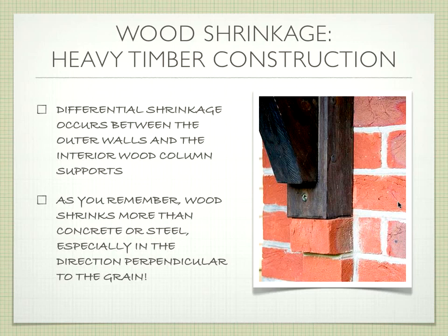If we go all the way back, I'm trying to review for you a little bit. The final's coming. If we go all the way back to the second lecture I did about foundation, we talked about differential settlement, where certain parts of the building settle more than other parts. And it causes issues. It causes all those cracks that are in your house. In my house, at least. The same thing can happen here, only this time it's not settling. It's shrinkage of the wood versus the non-shrinkage of the brick walls or the concrete walls. Okay, so we have to deal with that in some manner.